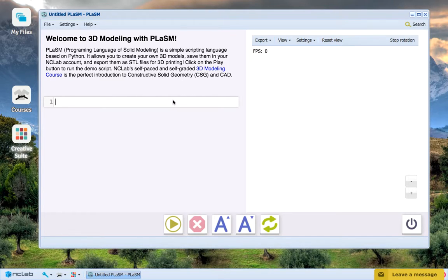And in the second, I will create a three-dimensional pyramid using the index values of a for loop to increment the size and heights of a set of four-sided prisms that we'll make with the cylinder command. I'll start by making the two-dimensional set of steps.